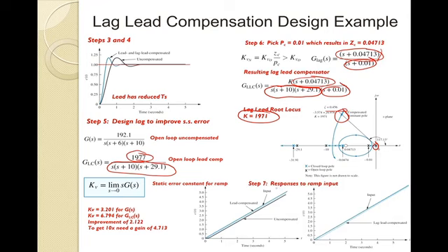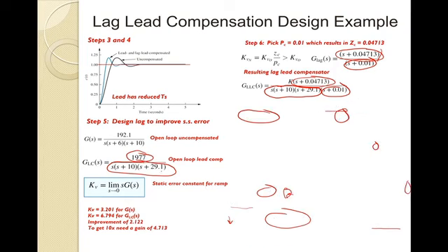So first, I'm showing the input here, with the uncompensated system in black, which is the lowermost line. The input is the uppermost line here, solid red, and the lead compensated, just the lead compensated, is this little light blue one in between. And then when I add the lag-lead compensated system, just comparing that to the input, you'll see that it matches pretty good. So if we were to do that comparison in the steady state, it's hard to just visualize that 10x improvement, which was, again, our goal.